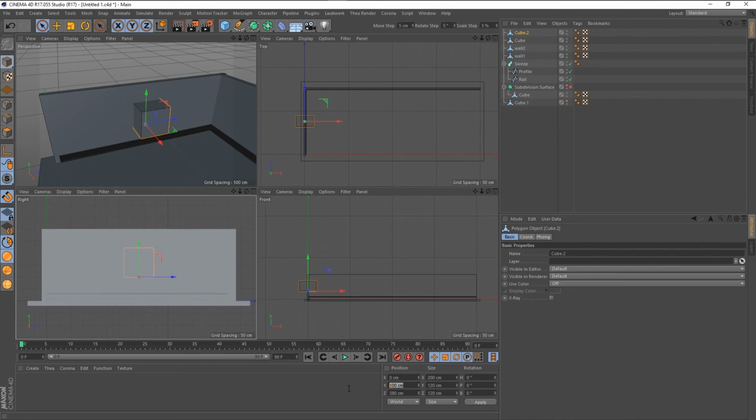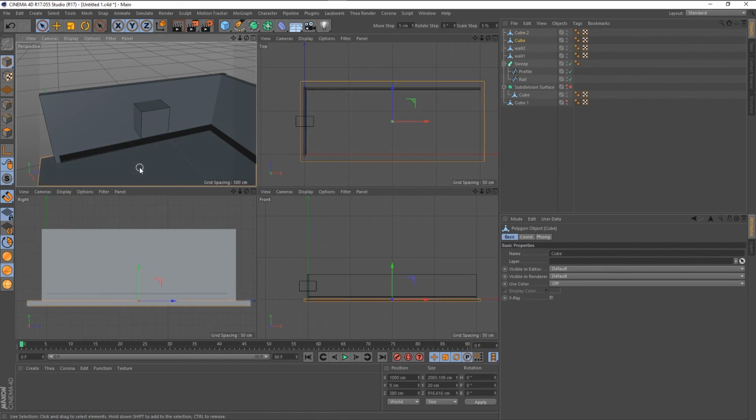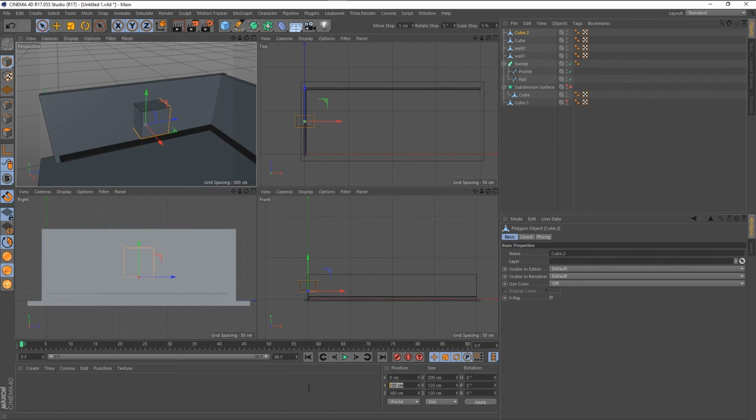Okay, so here we go, 100 centimeters above the floor. The top of the floor should be at 0. So yeah, so now we've got it accurate. So now our windowsill is at 100 centimeters, which is typical windowsill, 90 to 100 centimeters. We want to put it at 90, hit that, hit enter. And now we've got this cube, I'm going to call it window, let's call it window hole.